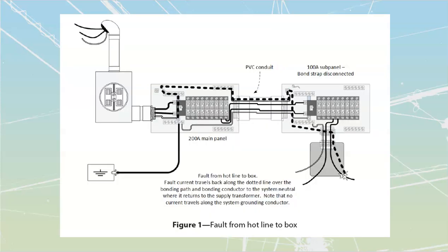Okay, so our Canadian Electrical Code has a number of different sections that we're aware of: grounding and bonding, general requirements, installations, etc. We're going to have one section that's referred to as Section 14. We often refer to this as PNC, or Protection and Control. Section 14 specifies when I need to have a protective device, and generally speaking, it's usually anytime that I've got an ungrounded line.